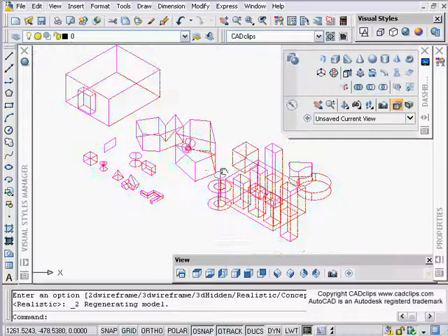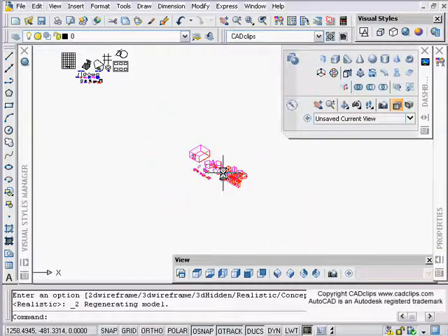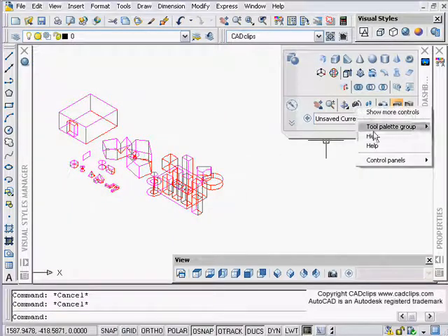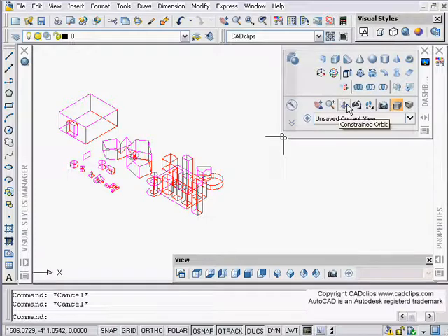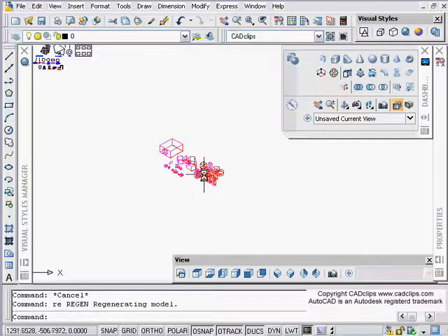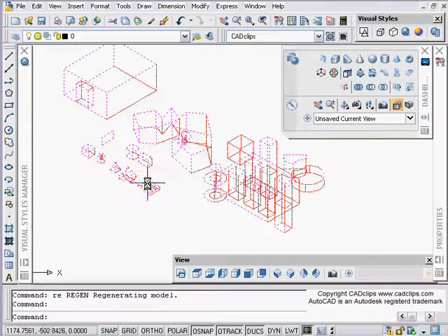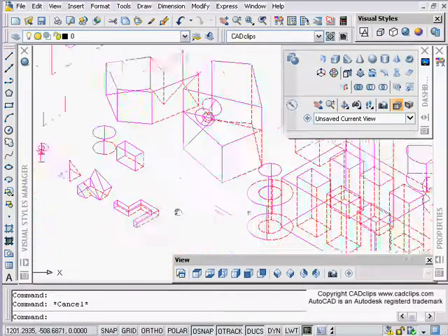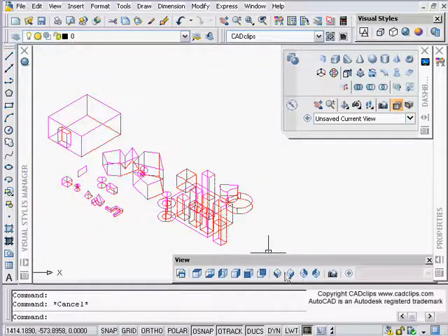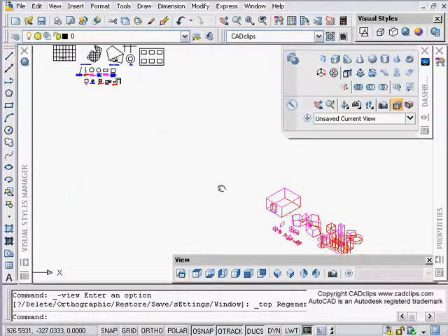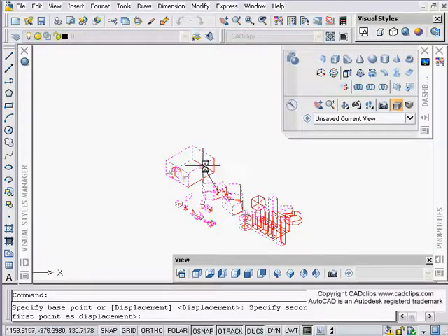obscured lines, okay, from that view that I created. And it appears I've lost my perspective aspect as well. Start this again. Not getting my orbit command, but now I've got that block, and you can see that I've specified my line types, etc., based on that particular view. Doesn't look correct from over here. You have to look from the top because that's the UCS it was created in.